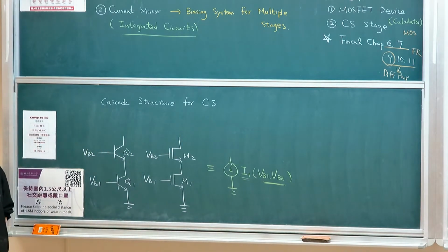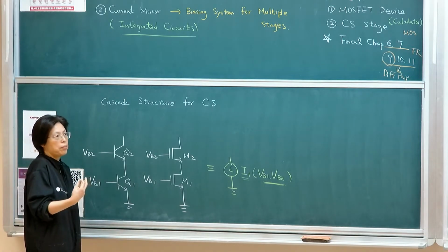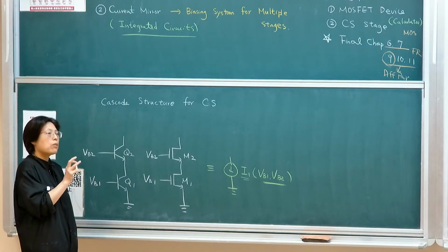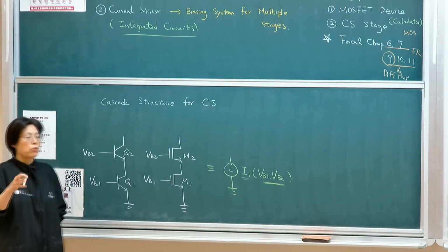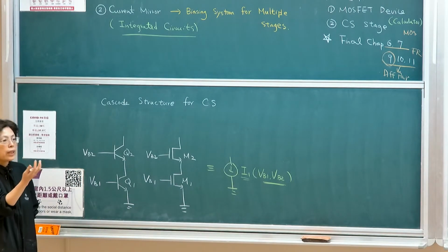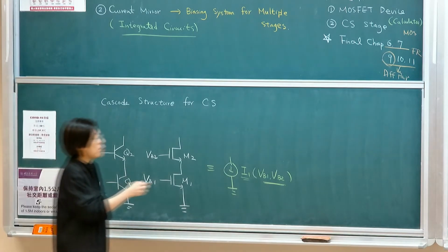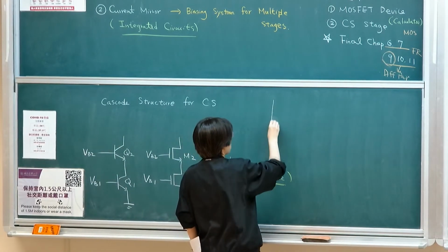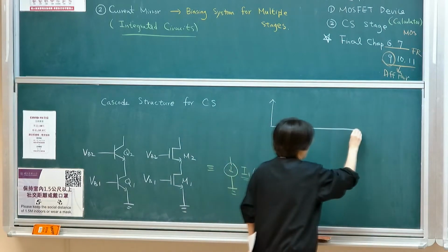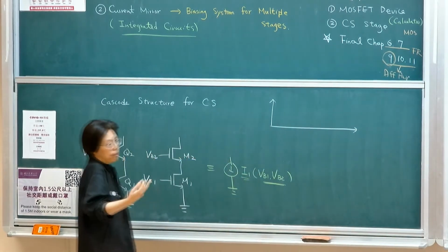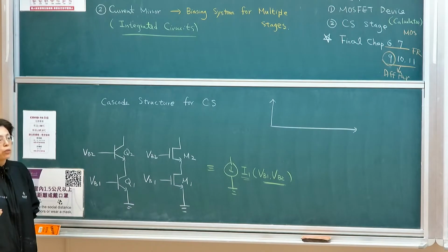What we actually look for in characterizing a current source is this: every time you talk about analyzing a circuit, you need to understand what the key parameters are that are important to describe it. For a current source, it's basically two parameters. This is the same as input-output resistance and voltage gain if you're describing a voltage amplifier.